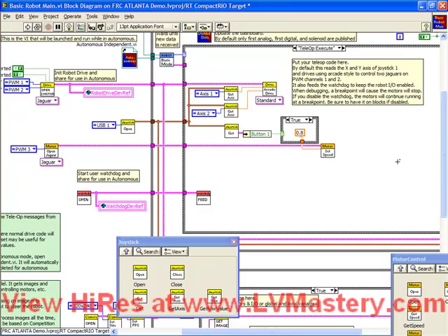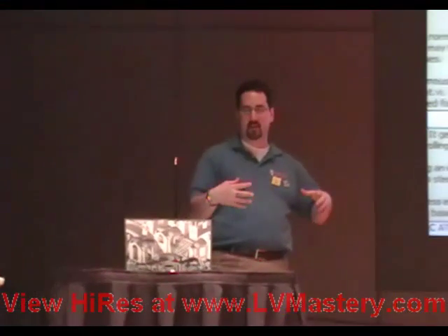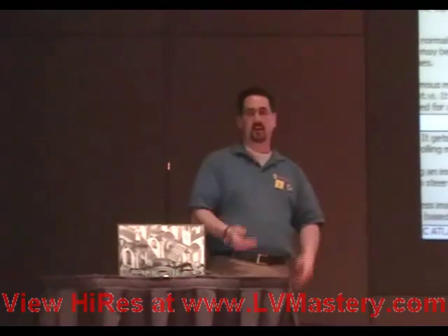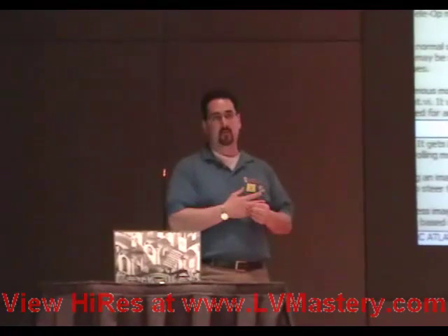If it's false, I'm going to put in a 0. And if it's true, I'm going to create a constant and put in a 0.8. So if you had a simple robot that all you needed to do was turn on a third motor with a ball picker upper, I'm sure that's not a real term, but I just coined it. When you push the button, it turns it on, you're done. You deploy this code, it will run on the robot, and you're ready to go.